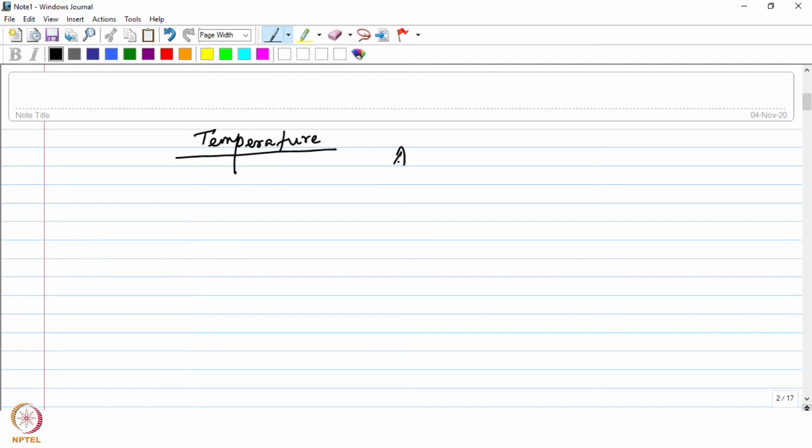For example, if you talk about aluminium silicon carbide composites, then with regard to the contact angle between silicon carbide and aluminium, you can plot the contact angle with respect to temperature and see at different temperatures how the contact angle varies with time.